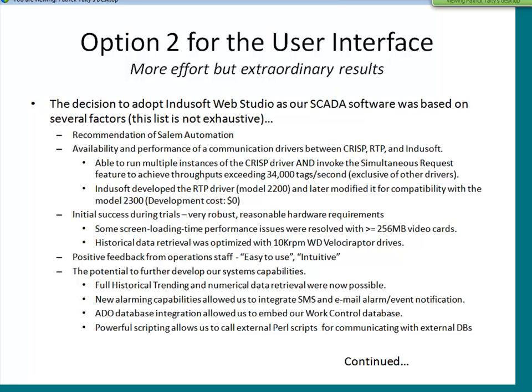But a number of things were done by InduSoft. One that I'll mention is the simultaneous request feature, which is something that would be of interest to somebody looking to do a large number of communication requests. Basically, what that does is it allows a single instance of a driver to run in a multi-threaded way, rather than just making a request between the SCADA and the host. You would make 2, 3, 4, depending on what the protocol and what the process control network can handle.